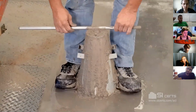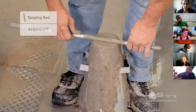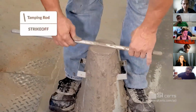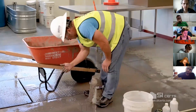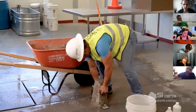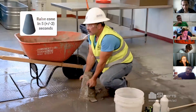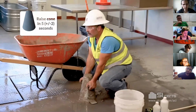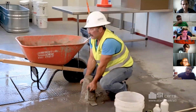With a rolling, screeding action, you'll strike off the top of the mold. The tamping rod is the only approved method for striking off the mold. Remove any excess concrete. We're going to raise the mold in 5 ± 2 seconds, clearing the concrete slump by 12 inches. You don't want any torsion or side-to-side movement as you raise this mold.